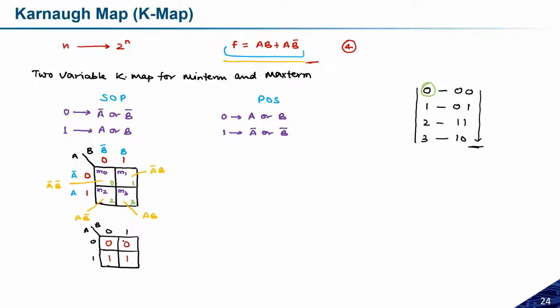This is how we represent the K map based on the function. This is important. If you see here, this function indicates A B bar plus AB. This is how we represent the sum of products form in the K map. Is there any doubt on the SOP form? Then I will talk about the POS, and we can discuss later. I will tell you later how we can minimize these things. I am not telling you how to minimize this one now.